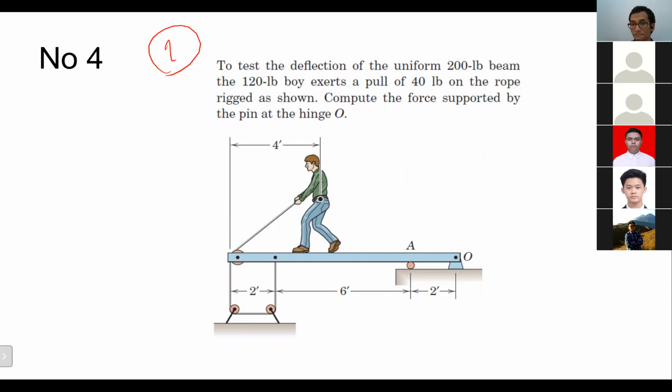Sir, is it because the angle between the guy pulling and the beam is not shown? The angle, yes, correct. That's one as well. Plus the contact force there, we are not sure about that. There is a normal and friction force here as well, so there is no data on that. That's why we have to choose the correct free body diagram to solve this particular problem.